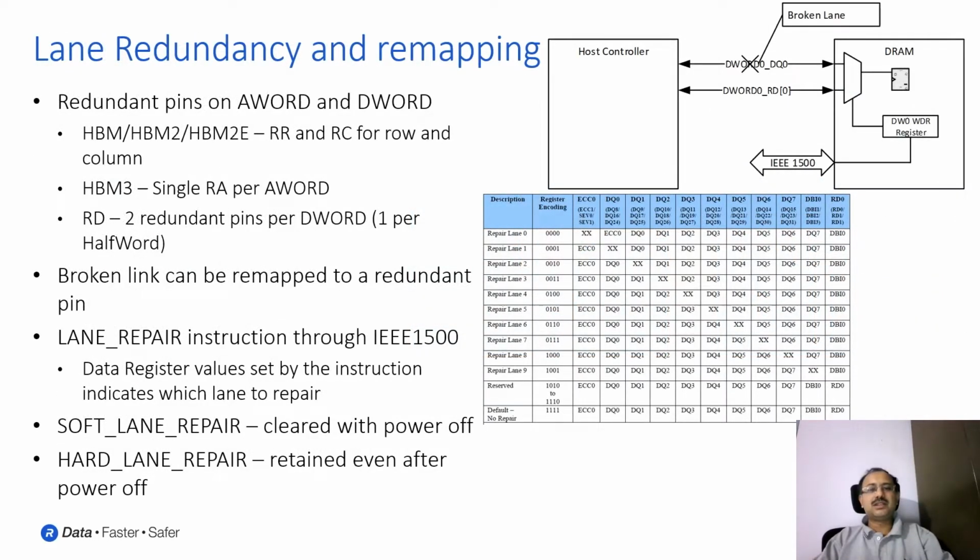So we have seen 2 methods to find out whether a link is broken or not. One is related to a physical connectivity check through DC and the other is through checking whether there is any lack of timing ability or the link is unable to run at the maximum speed possible. So what if there is a link broken?